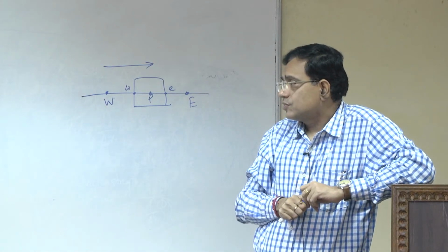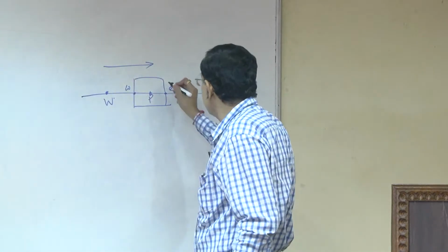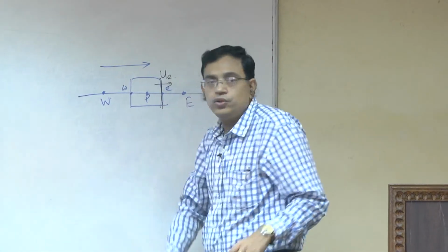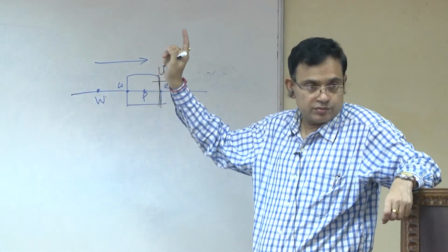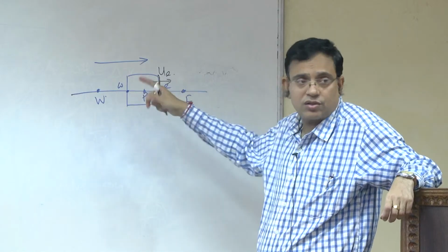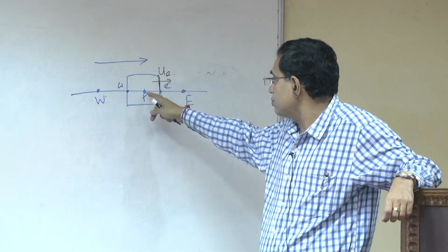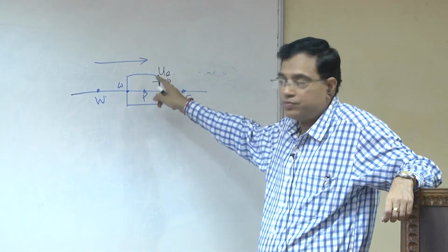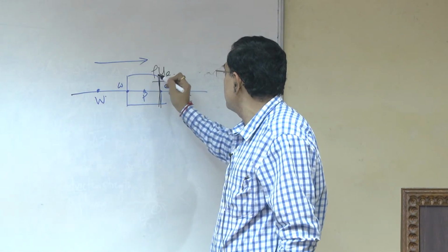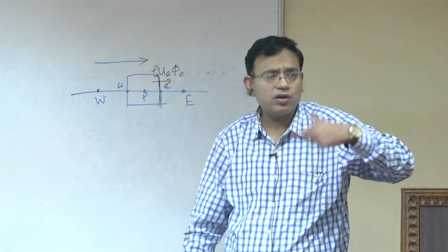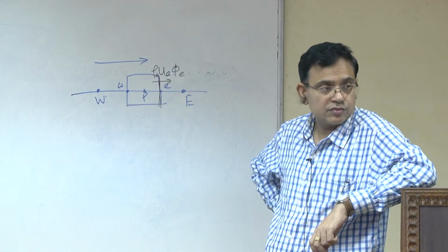What it says is, if UE is greater than, let us concentrate on here. You have something as UE. Your objective is to write an interpolation for phi small e in terms of P or E or a combination of that. In the central difference, it was half of this plus half of this. So, overall rho E UE phi E, because your main interpolation challenge is phi small e.